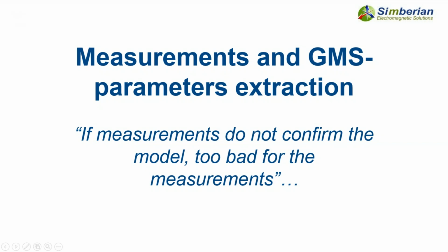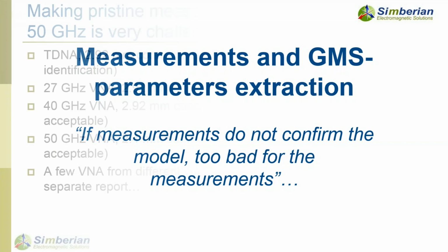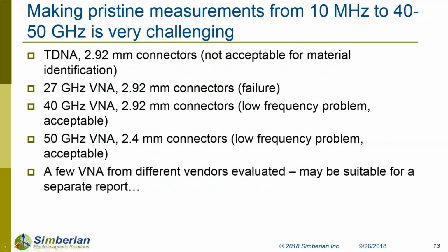Measurements and general product extractions. Well, when we were doing measurements on this board, it was really challenging. The board in the beginning was designed for a time domain network analyzer. Measurements with the time domain network analyzer were pretty noisy, above 10 gigahertz, which could not make our material extraction reliable. So we had to switch to different options.